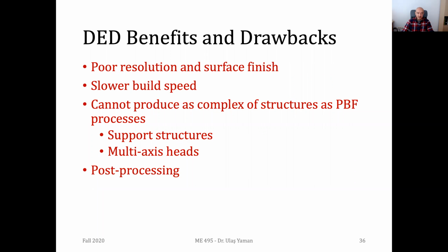And we need to do some post-processing after the part is fabricated. You need to clean the part, since we will have powders around the part. They may stick to your part, so you need to have a cleaning stage. And also, if you're not satisfied with the surface quality, you may need to do some machining to increase the surface quality.